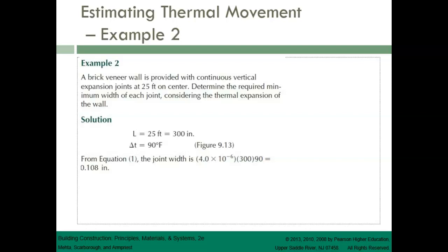So a quarter of an inch is going to be 0.25 inches. So that expansion is going to be less than an eighth of an inch. We'd probably just go ahead and make the width of that joint 3/8 of an inch.